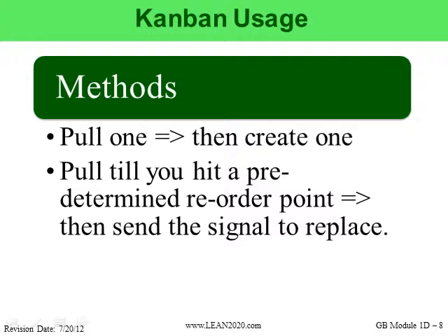We're going to produce product until the plating department hits a 600 panel backlog. And then we'll shut the photo imaging department off for a little while, or throttle it back, only producing the quick turn jobs or maybe out of position jobs, and again reducing the flow coming through that particular area. So there are different ways that we can use a Kanban.